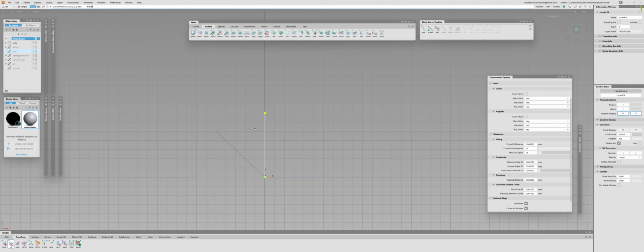After that, I'll type a colon, and then I will enter the subunits, the minutes. To understand: 1 degree is 60 angular minutes, and 1 angular minute is 60 angular seconds. You can open up the calculator and calculate it, but I actually did it for you. To rotate it by 45 degrees in minutes, you need to use 2,700 minutes. Let's hit enter, and as you can see, it rotates by 45 degrees. Now, let me turn that back.